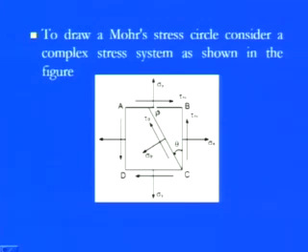We simply cut the plane at theta. PC is the cutting plane, which we simply cut at the theta angle. This is our angle of measurement. We just want to measure those things, and at this particular PC plane, normal to this plane we have a normal stress component, that is sigma theta, and we have a parallel stress component, that is tau theta. This means the normal stress as well as the shear stress components are there.